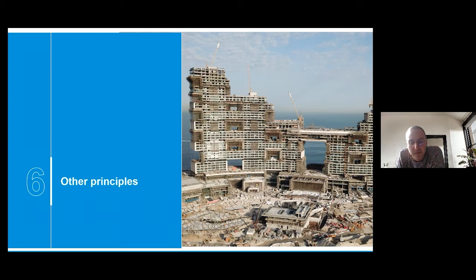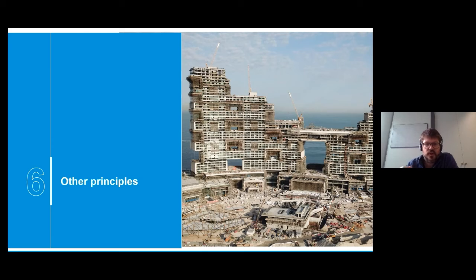To be honest, we don't take it into account in the mix design when we are doing it, and I'm not saying that it is the right thing to do. I'm really talking about what we are doing on site. But as soon as it is important, as soon as we have the mix design, we are doing creep tests to know exactly, and then we are working together with the design office to see what the impact can be. But yeah, to be honest, we don't work that much on this in the mix design. Okay, I cannot say if it is the right thing to do or not, but this is how we do it.